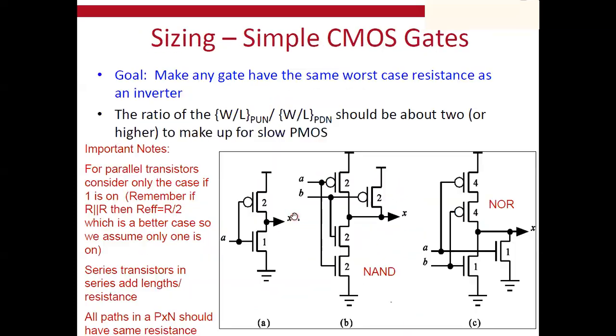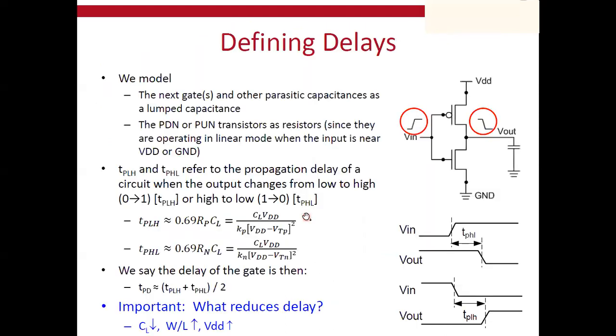So simply, we can say that these are what we can call delays associated with the logic gates, either from the input terminal or from the output terminal. From the input terminal, let me go back to this important slide. Yeah. So from the input terminal here, you have an input capacitance which will affect this TP high-low value, and the higher the fan-in, the higher the TP high-low values.